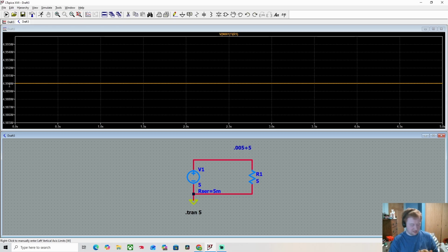But let's say that you are very, very nearly 250 watts. You might see some voltage dips because nothing upstream is perfect and nothing downstream is perfect. That's why 19 volts is called a nominal rating. And it actually might fluctuate between 19 and a little bit less than 19, maybe a little bit more than 19. It all depends on how the power supply works.